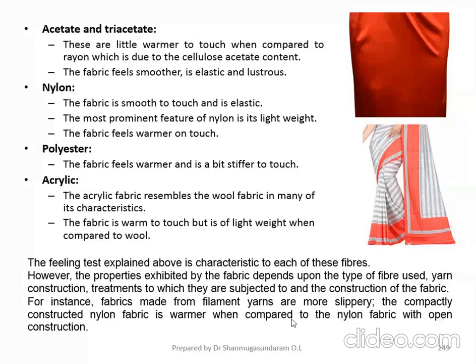The fabric is made out of nylon yarn only, but what is the difference? The compactly constructed nylon fabric is warmer when compared to the nylon fabric with open construction. Suppose you construct the fabric with low ends per inch and low picks per inch, you may not get this type of warmer feeling.